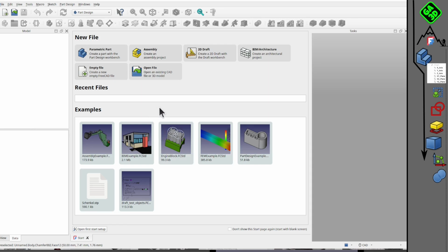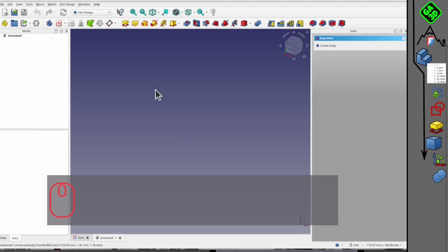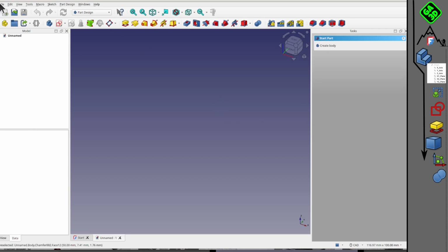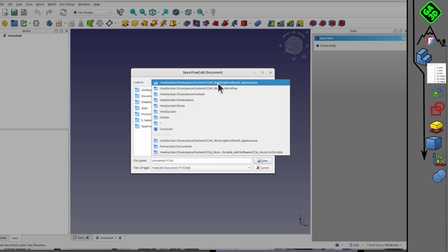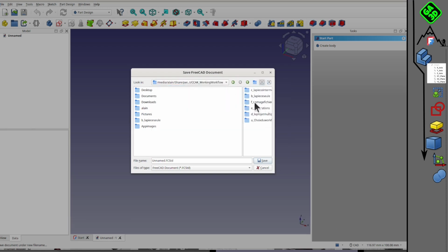You can download. It's never in FreeCAD format, but there are always STEP files that you can bring in, which work very well, and which are the standard exchange format between the different CAD programs. Then you select the item you like. You have the little list. Well, that's a bad example, where there is only the SolidWorks file. But we're going to look at this one here, where there's a STEP file you can download. And then you have your 3D.